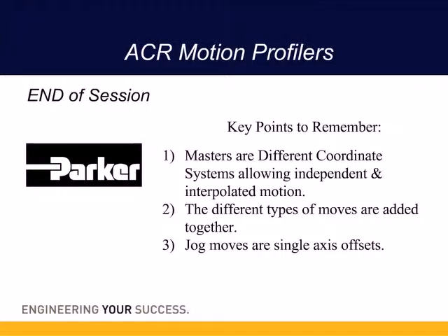This is the end of the ACR Motion Profilers training. Key points to remember are: 1. Masters are different coordinate systems, allowing independent and interpolated motion. 2. The different types of moves are added together with Setpoint Summation. 3. Jog moves are single-axis offsets.